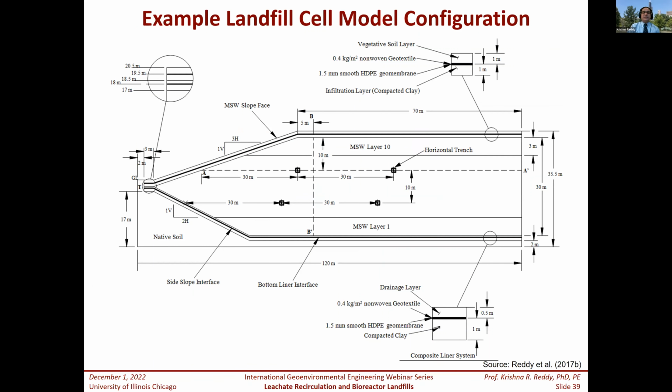So if you can do that, then you will be able to predict what happens in a bioreactor landfill during the operations. So for example, we took this model and applied it to a typical landfill, which is in my state, Illinois, close to Rockford. We took just the same profile. We did a lot of field investigations on this site. So we got those properties, and this is the landfill cross section, and we assume these are the leachate recirculation wells, trenches, and we have a liner system. Everything that is at this landfill is modeled.